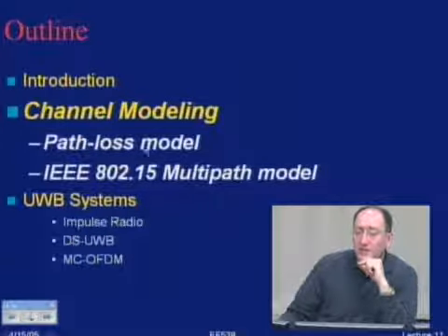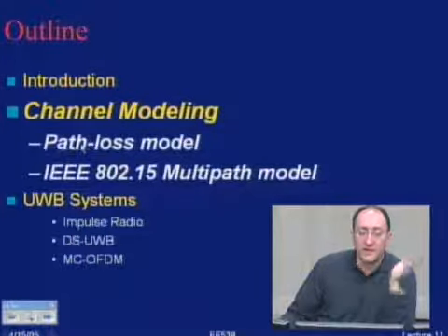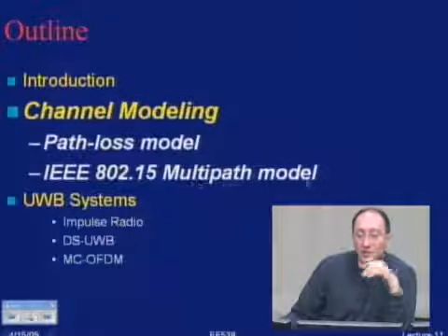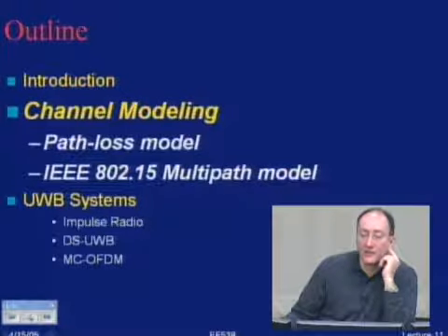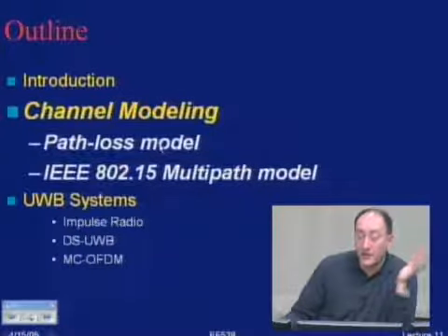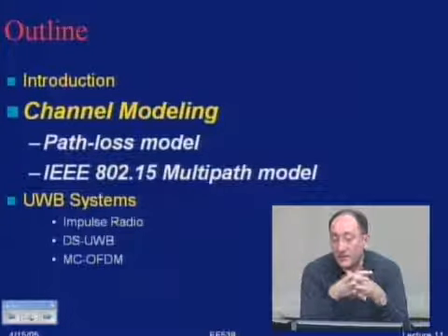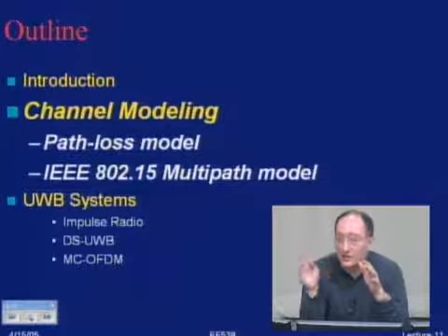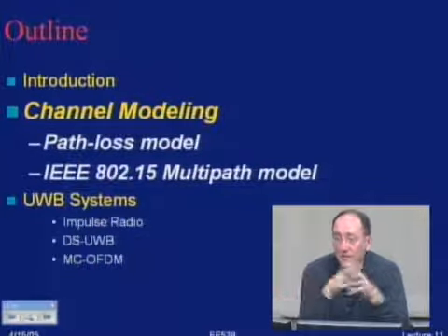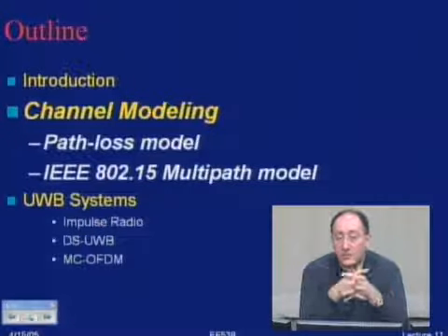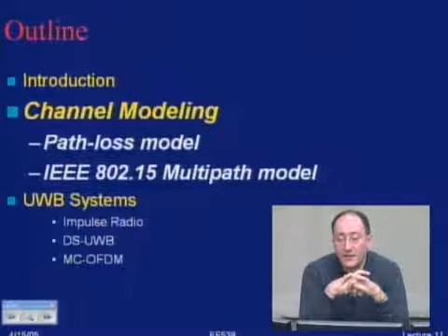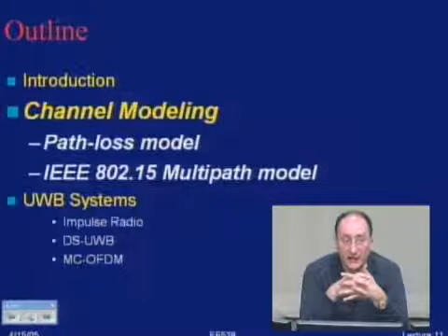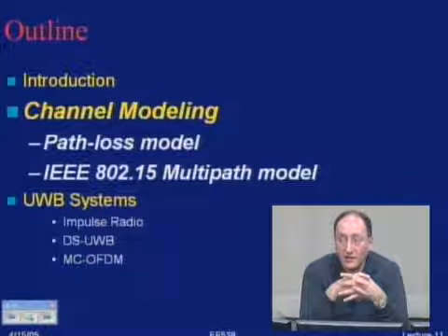For channel modeling, basically, we need two models. A model for path loss, which gives us the coverage, and models for multipath. If you remember, for path loss models in indoor areas, which are the areas where ultra-wideband technology is used, we had these distance-partitioned models. The same models are also used for ultra-wideband. Then, for measurement systems, again, we have similar measurement systems. The only thing which is changing is the antennas.